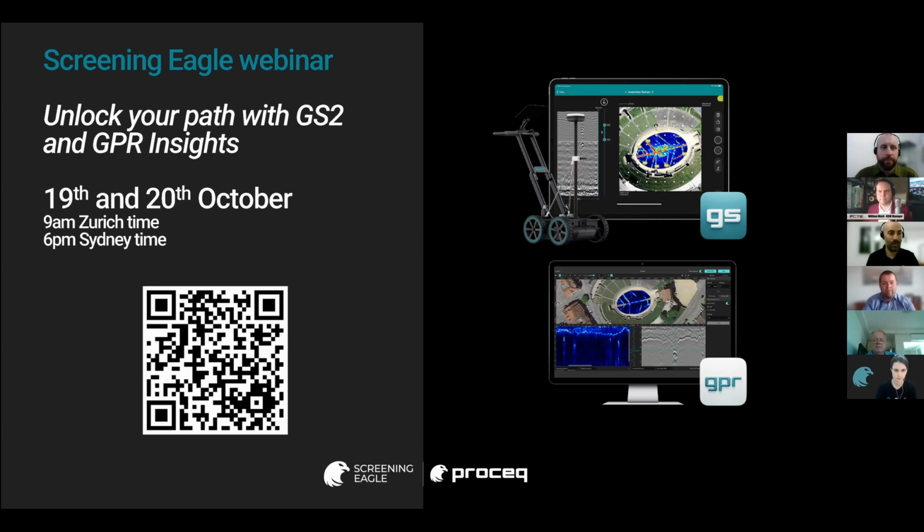So thank you. No, thank you very much, Alex. It's greatly appreciated. There's some good examples there. Just a couple of questions I've been answering in the chat, mainly about the different kinds of targets and distinguishing them. So certainly, depending upon where targets are, you can distinguish between metallic and non-metallic targets on radar data. But between metallic targets of similar size at similar depth, they're going to have very, very similar reflections. It's going to be very hard to distinguish between those.